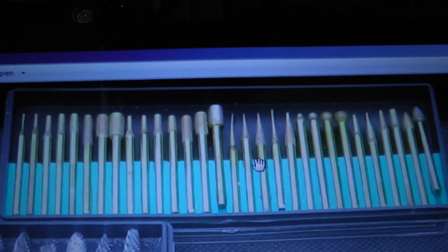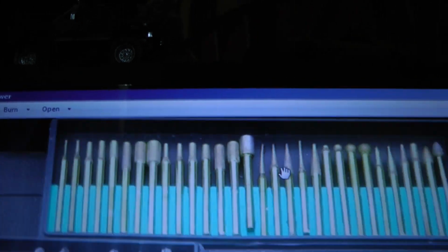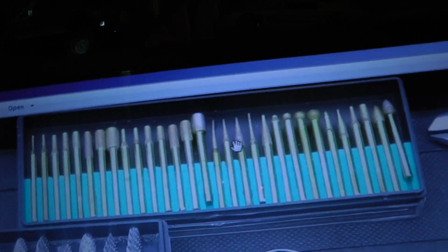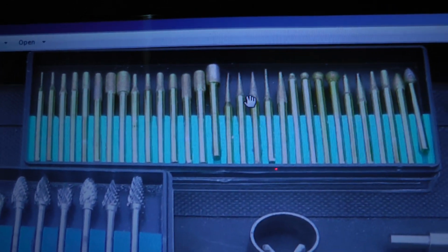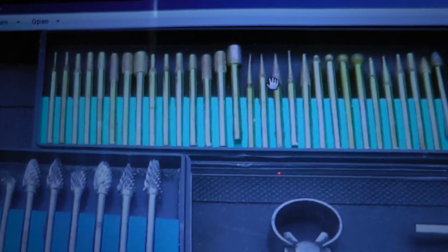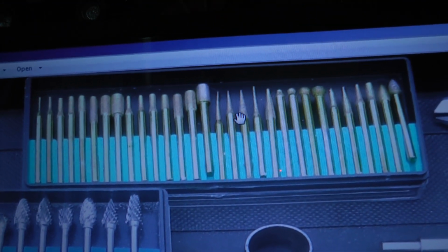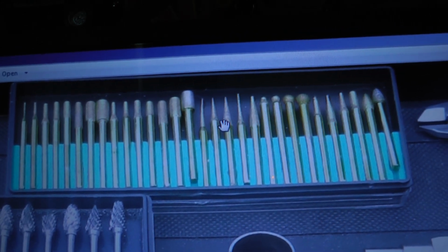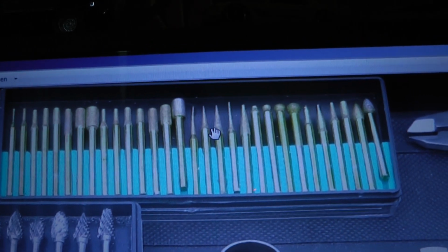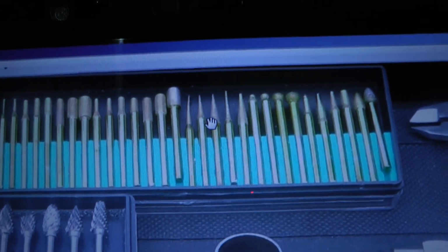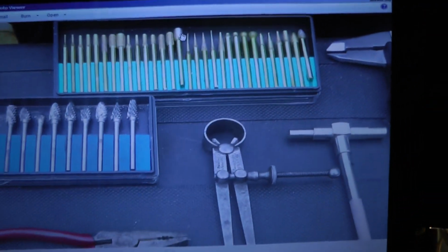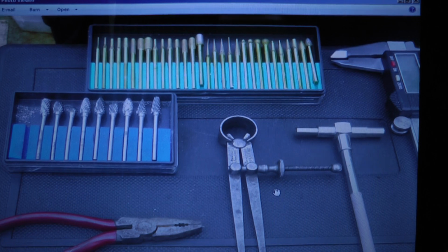These are just to polish, like a 250 and a 600 grit, another $14 item. You don't need to polish tunnels. That's kind of a misconception. Chambers are different because of detonation, but it's better to have a little porosity, like has been proven with dimples, is that you can increase velocity by having a rough surface.